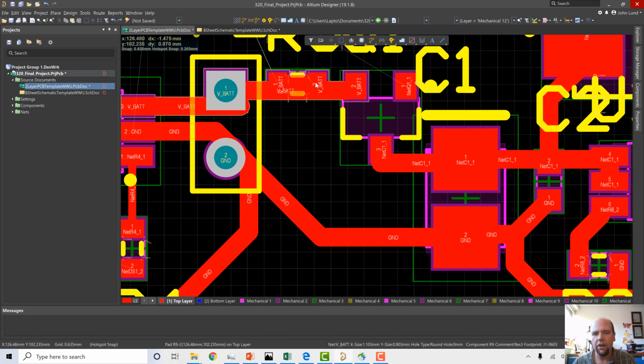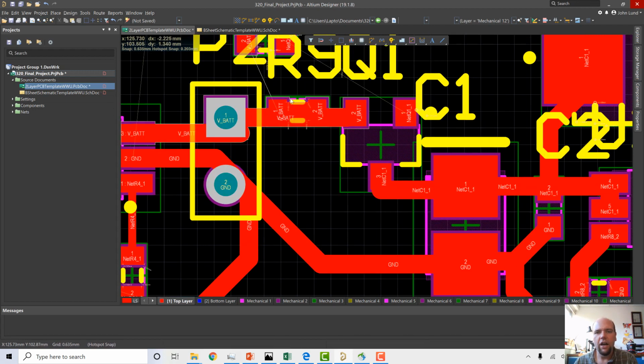So we could either jumper solder over here or jumper a 0 ohm resistor over here. And this just gives us a little bit of a tool to break a part of our circuit away from another part of our circuit and then reconnect it after we're done prototyping it. And ultimately, you can take this out. If your design works and you're done with it and you don't need this, you can take it out later. But it's kind of nice to have these at certain places in your circuit.